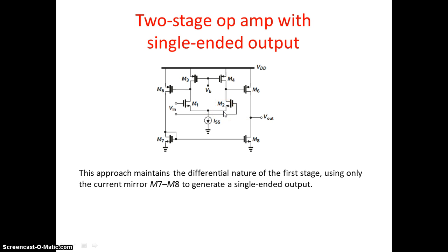As we have already discussed, the voltage gain it produces is going to have a two-sided effect. If you recall the active current mirror load circuit, whatever changes it produces across this terminal are reflected across M7, and the same is reflected here. Then at the output stage it is going to produce more swing.